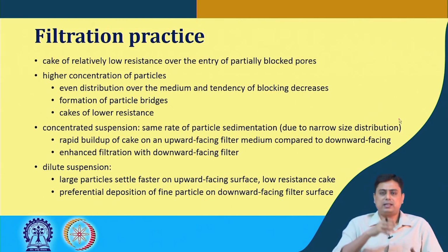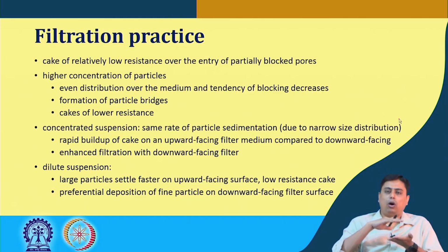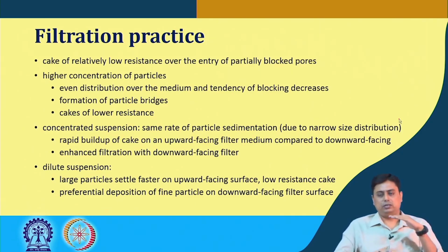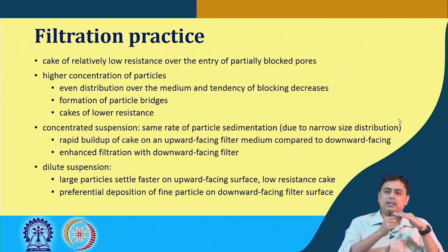That means the particles are settling approximately all at a time, so there will be a rapid build-up of particles on the filter surface compared to when it is facing downward, because then the particles are basically sedimenting away.